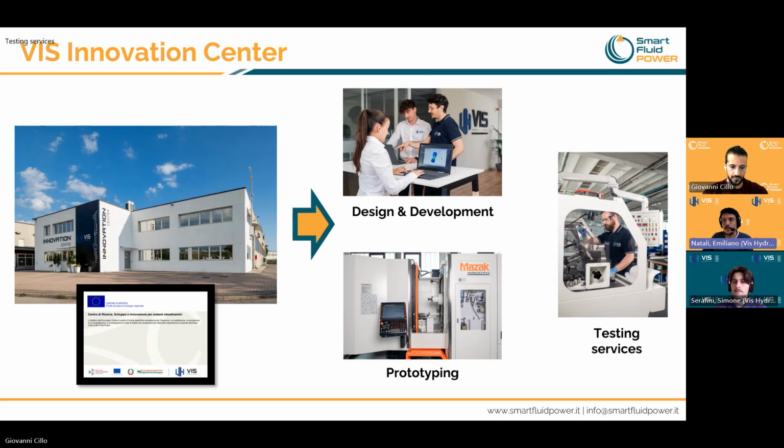Today, we use several simulation technologies as part of this process, such as CFD, FEM, and electromagnetic analysis. In recent years, however, the introduction of lumped parameter simulation based on OpenModelica and the SmartFluidPower library has been a real turning point in how we design valves. By building the dynamic models of our valves, we can evaluate their behavior already during the concept and design stage.